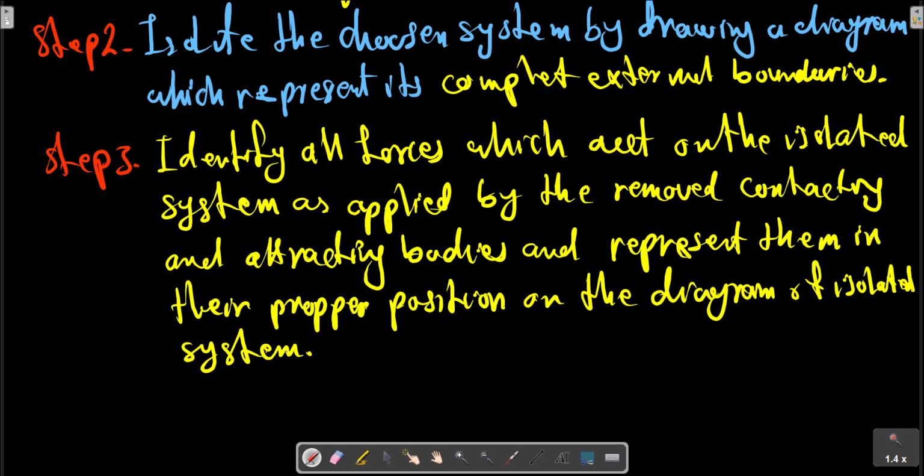Make a systematic traverse of the entire boundary to identify all contact forces. Include body forces such as weight where appreciable. Represent all known forces by vector arrows, each with its proper magnitude, direction, and sense indicated. Each unknown force should be represented by a vector arrow with the unknown magnitude or direction indicated by symbol. If the sense of the vector is also unknown, you must arbitrarily assign a sense.